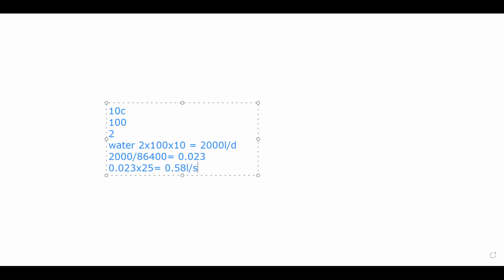If I want to design this now, only this now, all of us know what it is. I go to my design chart now. Since it's less than 1, I'll use the value for 1. But I need to know the slope. So I have to go back to that chart and get the slope. And it's very possible to get the slope because the elevation is given. Why can I know the slope? Because I have the elevation. So we're talking about 6 to 13. This is 6 to 13. 6 to 13 has a length of 210 meters.